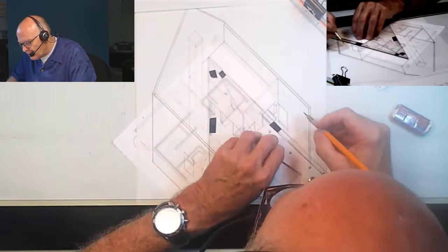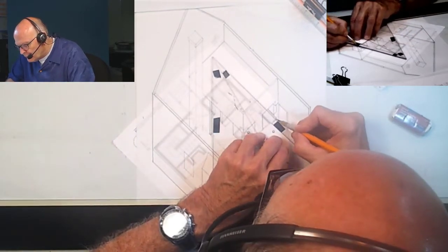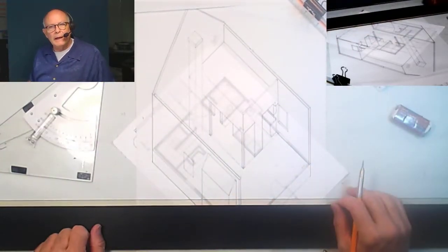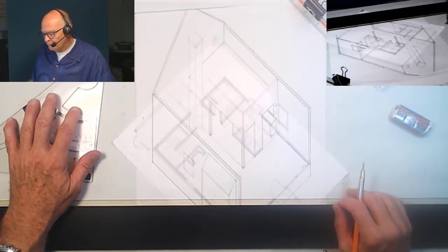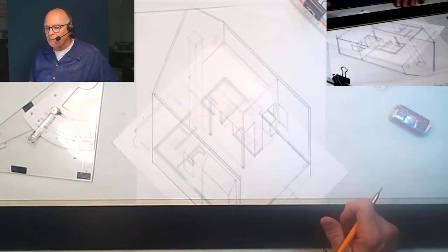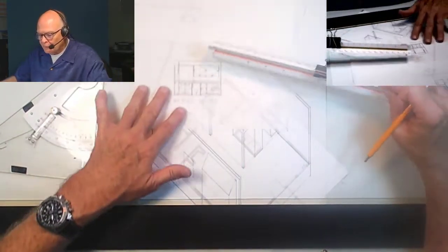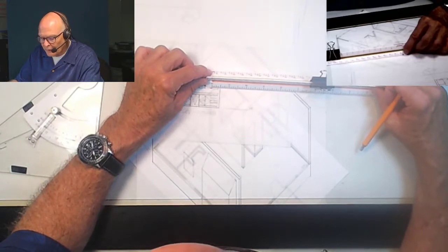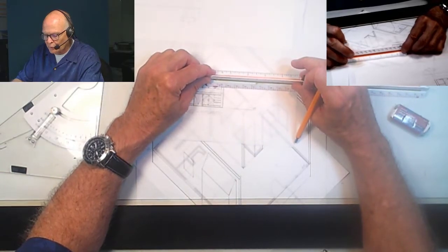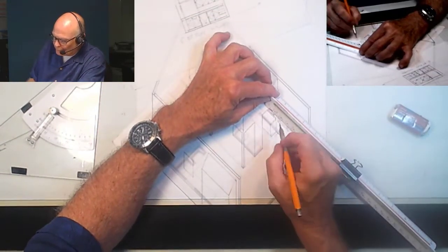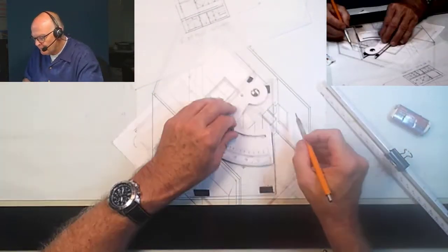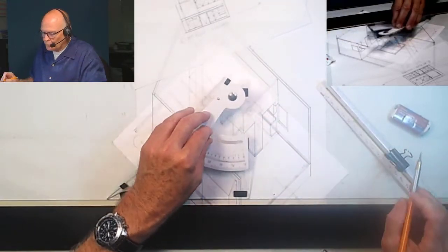And believe it or not, it does have a thickness. I'm not going to get too carried away with this, but understand that that backsplash goes up the wall, and you probably have one in your home right now. Okay, so what we have is the base cabinet and the overhead cabinet above that. And the overhead cabinet, if we just simply scale off the size, I'm going to change my scale here, it looks like it's about 1'6". And so I'm just going to measure from here along that angle, 1'6", and it's going to take me to there. And there's where that door is.